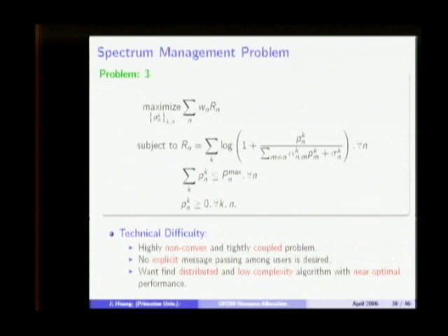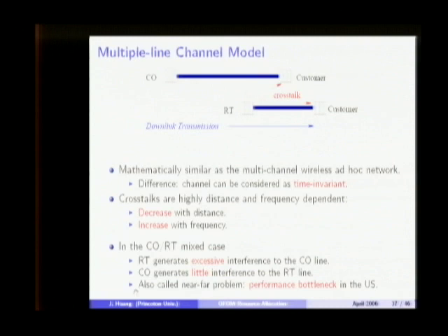But isn't this power allocation happening in one of the central offices? It happens distributively at the central office, the remote terminal, and the multiple remote terminals, at each transmitter. So one practical question: when a lot of bundles go through a remote RT, don't all of them get retransmitted again? If that's the case, then there is no one-way interference as such, right? So the question is, for example, all lines leaving from the central office should see symmetric interference. Good question. How much are the same?